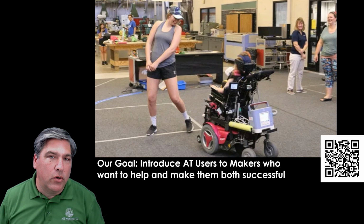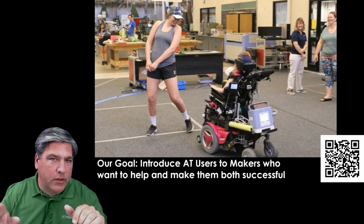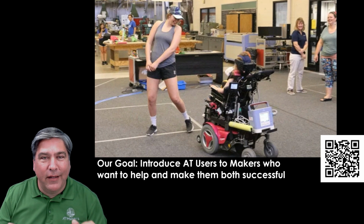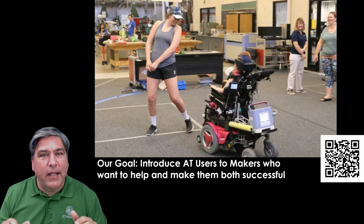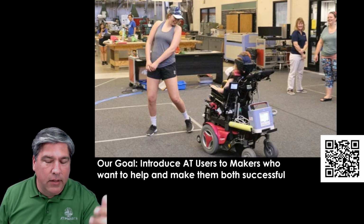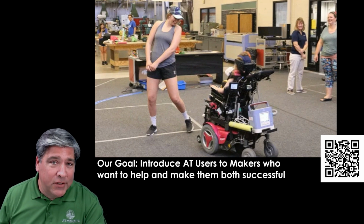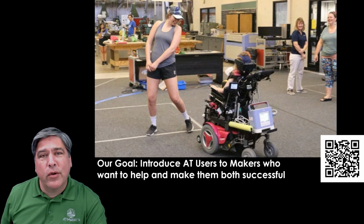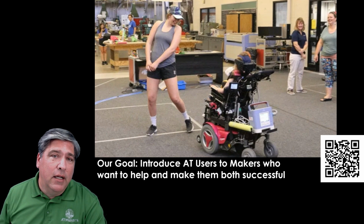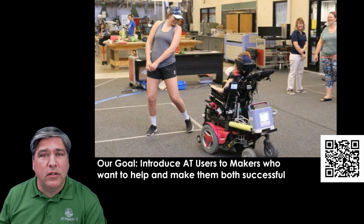And so we worked with her and her family to make the ability for her to control the chair with 2 switches. So right turns right, left turns left, both goes forward. And with some timing and things we'll talk about later, a little bit of logic made it possible for her to drive. And I did that with a group in Elkhart, in Mishawaka, Indiana, called Penn High School, Team 135. I worked with a robotics team to help me get that installed and do updates on it, and also to work with Ella and her family so that she would have the ability to practice.